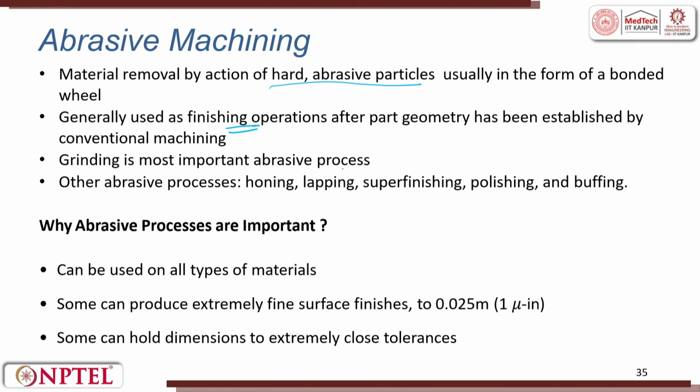Grinding is a very important process, and like grinding, we also have other processes like honing, lapping, super finishing, polishing and buffing. All these things are almost the same. The only difference can be that the abrasives are loosely held or rigidly held.